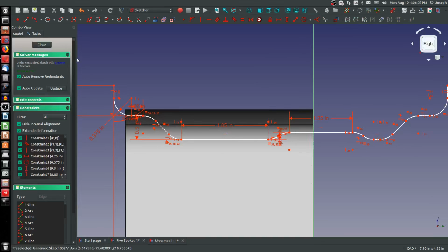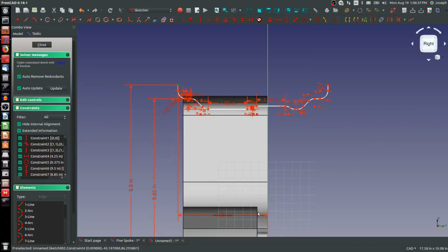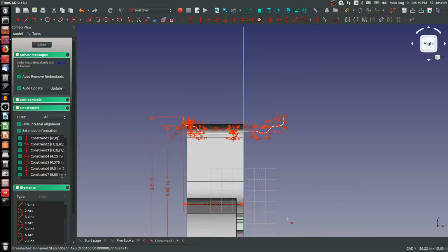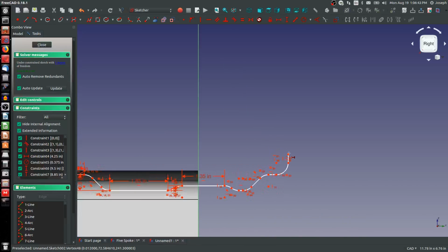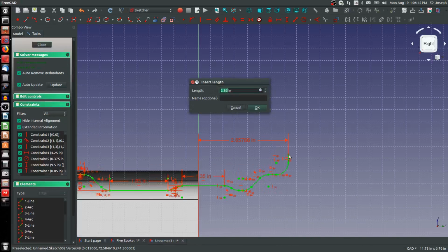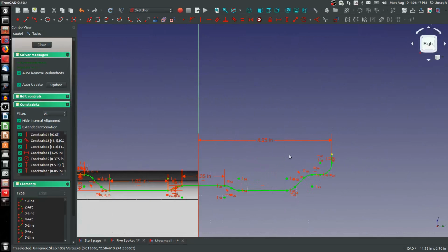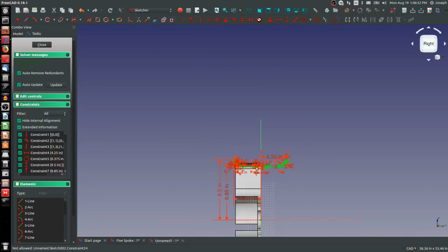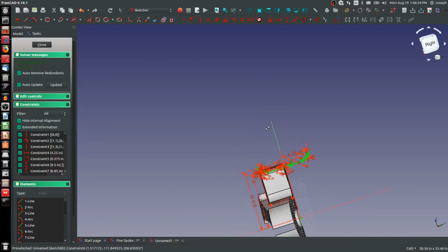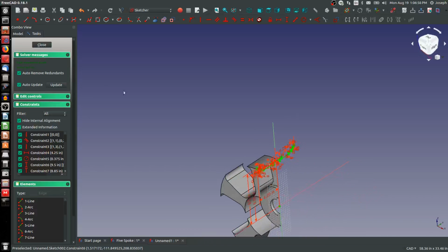And let's add an overall distance, Shift H. Actually, since I added this distance down here, 4.25, let's do the same. Again, that makes it 0 offset. And of course, we don't have a symmetric profile here like many wheels don't. So that ultimately gives us an 8.5-inch wide wheel.